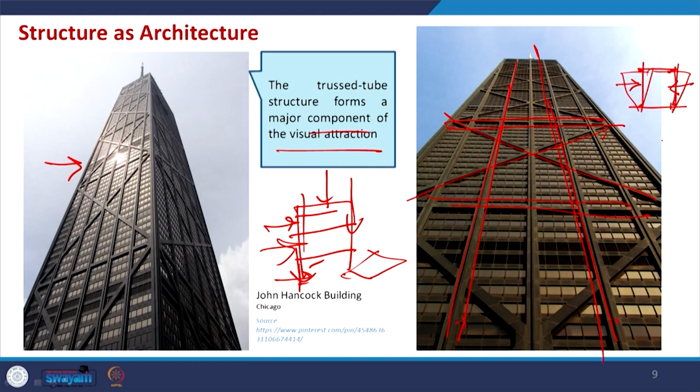Now, you just make an addition. So, the same frame, you take another matchstick and connect it diagonally, and then try to put the pressure here. You will see the deformation, this sway will be minimized, and if you add from this direction, it will be more. So, this is basically called structural bracing. Here it is for the lateral force, and placed vertically,